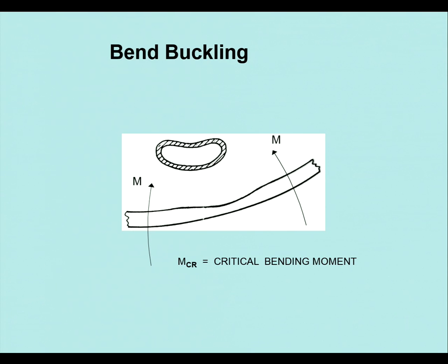Now, if you start putting a big concrete jacket around it with reinforcing bars in it, concrete doesn't like going in tensile, but it only loves compression. So what happens is the concrete will crack unless you've got the reinforcing bars in it. So you will actually get a shift of this axis downwards if you bend it. So that's the concrete around the outside.